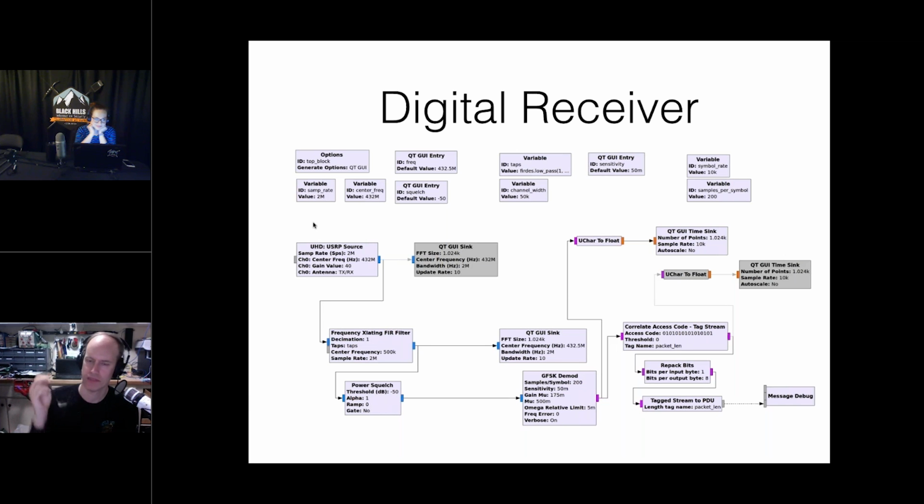So this is what I would start with, because the way RF works with respect to receiving it with antennas is that the length of the antenna is going to influence what frequencies it's good at picking up. So if you're trying to pick up a lower frequency, you'll extend it, and for a higher frequency, you'll retract it.